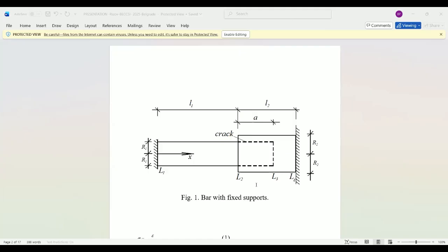Since the bar has nonlinear elastic behavior under temperature change, the complementary strain energy is used for deriving the strain energy release rate. A variety of graphs revealing the influence of the temperature change and other parameters of the bar model on the strain energy release rate are presented. The bar studied in this paper is depicted in figure number 1.